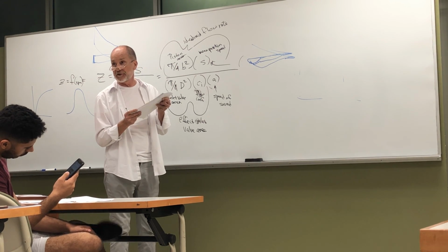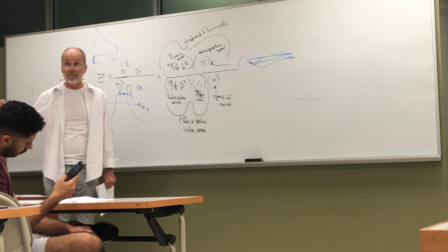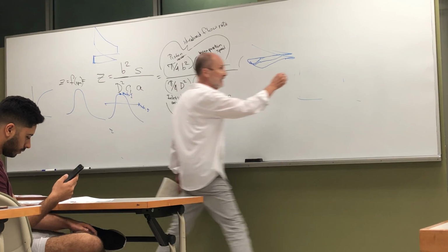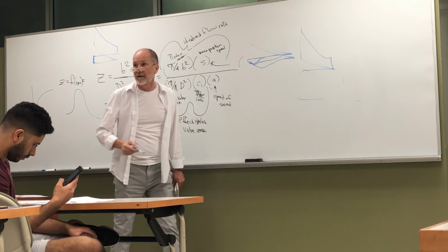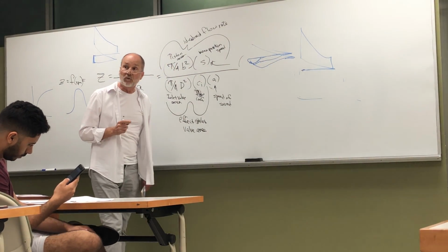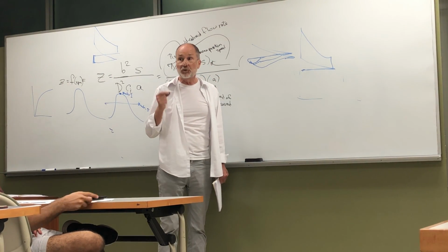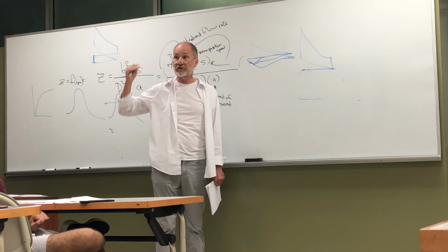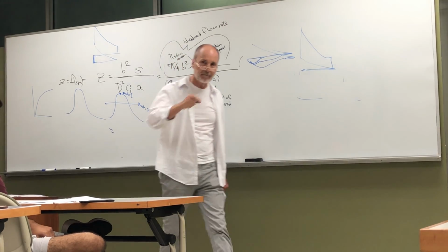Mach index 0.2 with manifold pressure 7.4. If we have the manifold pressure at wide open throttle and both manifolds at the same pressure, we're not going to see anything. Then our idealized one looks like this at wide open throttle, and these both take place at the same pressure. But if you want to see it look most similar to our idealized case, you have to assume that the pressure drop during the intake is negligible, and that occurs at the lowest Mach index number, which for this figure is Mach 0.2.